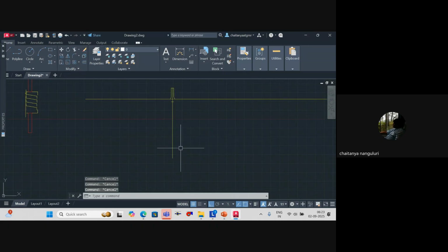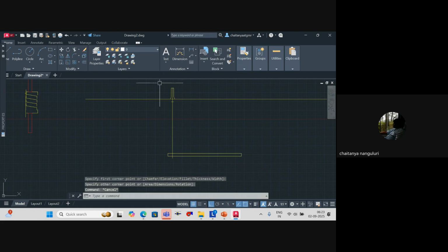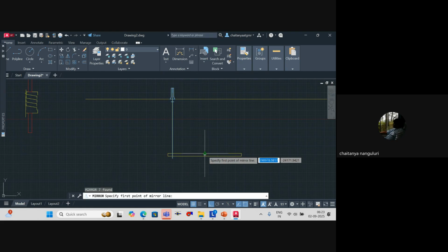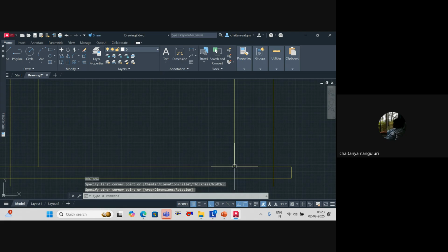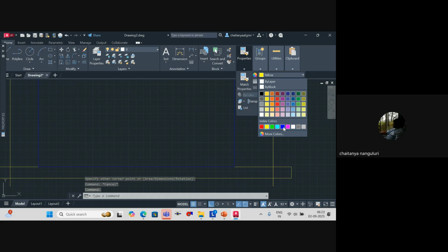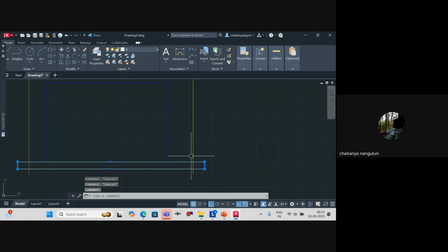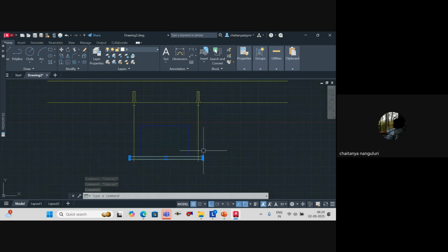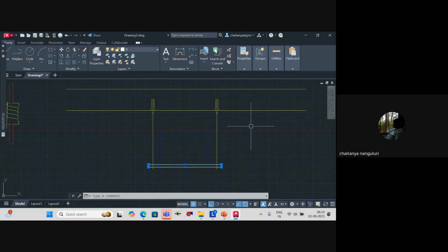These are your threaded rods, and then you'll go for the slotted channel like this, and one more threaded rod will be on the other side. Here you will place your ducting. Let's say this particular one is your ducting system. So this will be a slotted channel if your duct width is lesser than or equal to 1200. If it is more than that, you go for an L angle. Understood or not? Am I clear?